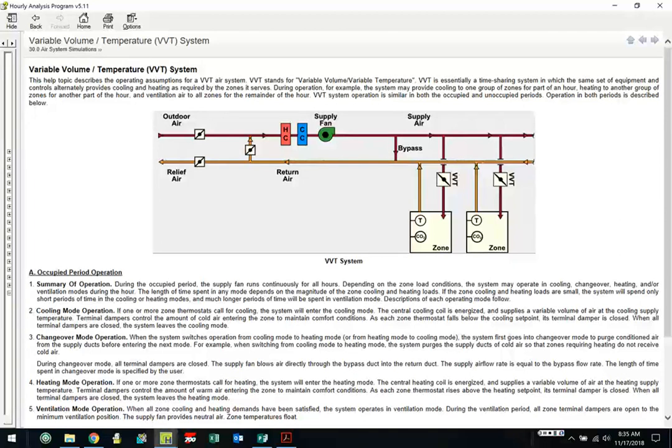So when I do that, if it's a single stage unit, you get the full heating capacity out of the rooftop, and air would be coming across down here. It could not go through these 2 dampers because they're closed, because I'm not calling for heating. It would go down the ductwork and go into the rooms themselves or into the zones themselves. Now what tends to happen is if I don't get enough airflow across here, instead of stressing the heat exchanger here or freezing the coil, I would be monitoring duct pressure.